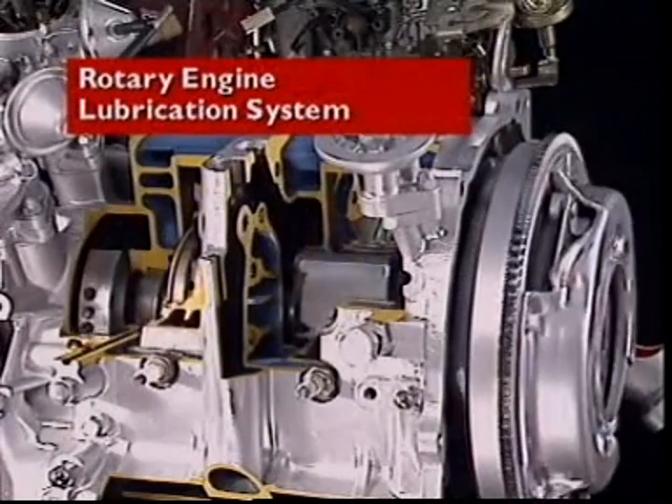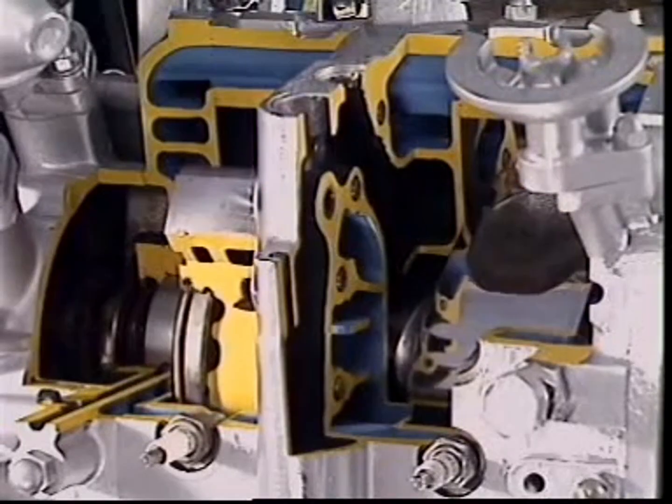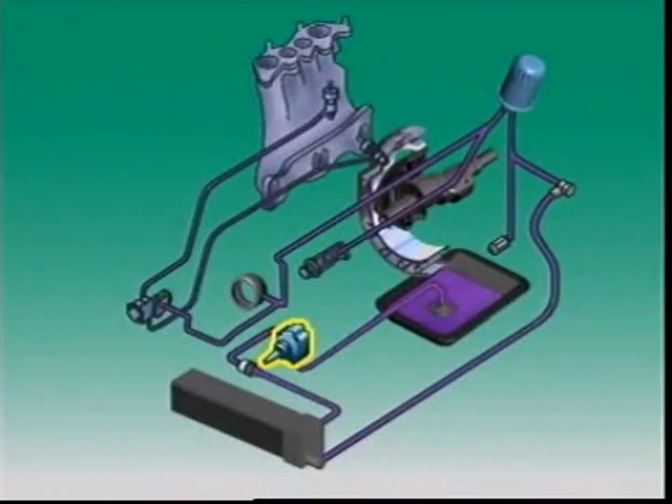Let's look at the rotary engine lubrication system. Its main lubrication system is similar to that of a four-stroke petrol engine. An oil pump picks up oil from the oil pan through a strainer and delivers it to an oil cooler on the front of the engine. The oil cools, then enters the oil filter at the rear of the engine.